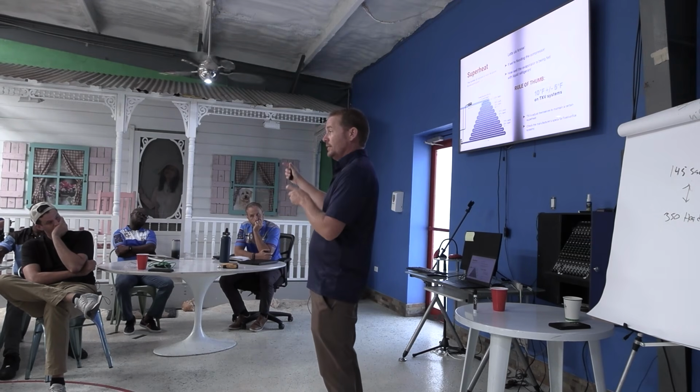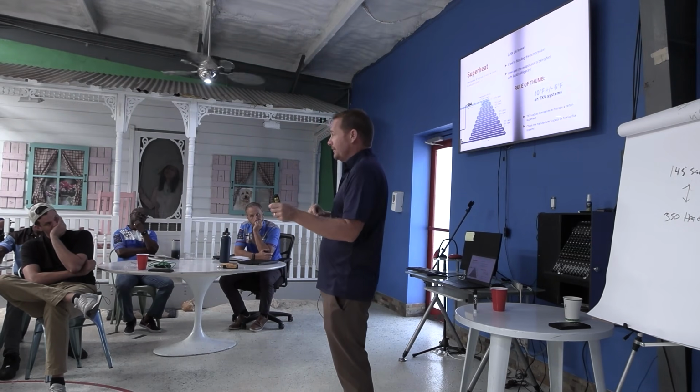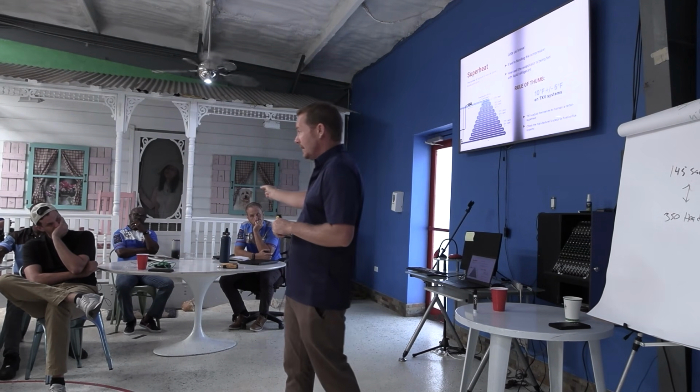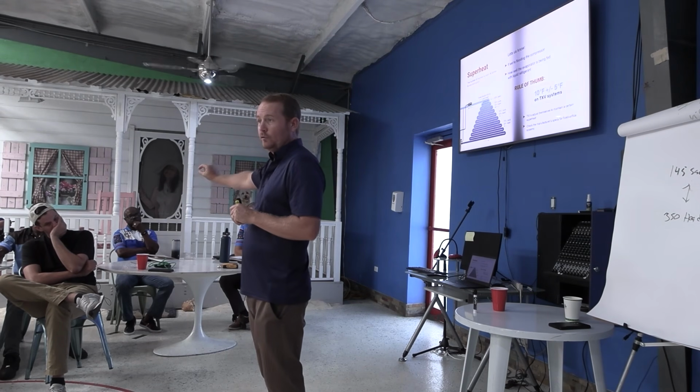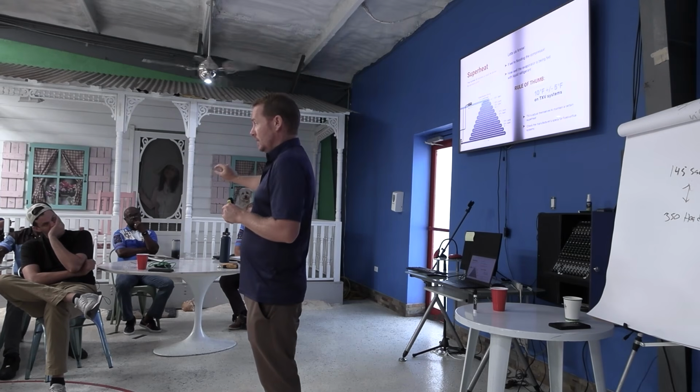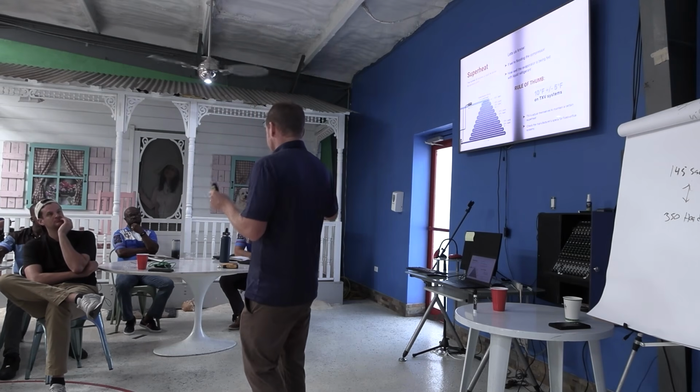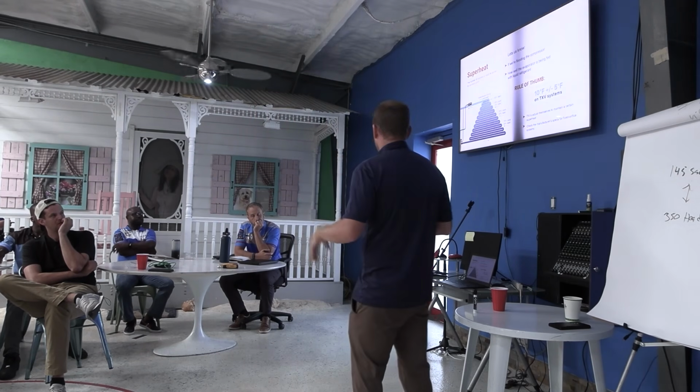And the same thing is true with a fixed metering device system. If you have a piston system and you're charging it by superheat, I still want you to measure the subcool. I still want you to know that you have a full column of liquid in the liquid line. It's important to know that. That's the 5 pillars. Make sense? Okay.